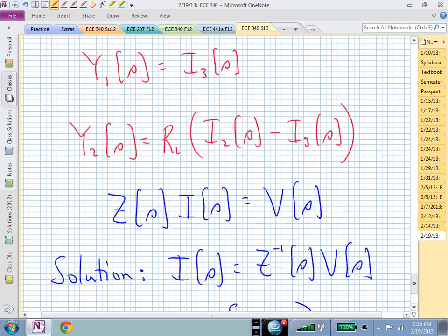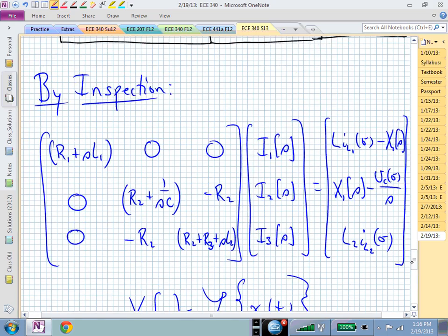Now, all we really did, if the matrix part confuses you, don't go there. Just stay here. Just stick with this. It's still, though, a matrix. If that messes you up, just write all the equations out. And just say, here's equation 1, and that's the top row. Here's my second mesh, and that's the second row. Here's my third equation, and that's the third row. Now you have 3 mesh equations. I was just trying to show you a new way to think about doing circuit analysis by inspection in the S domain. And then you can sort of just mechanically follow that process.